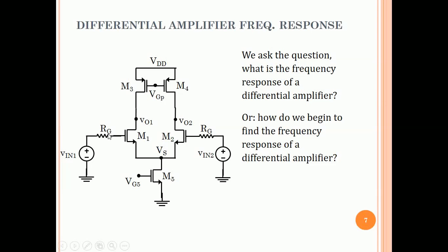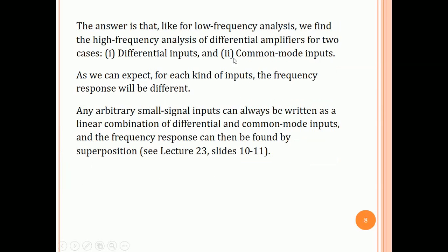The answer is actually simple, but you are given a circuit and you are asked, well, find the frequency response of this circuit. That one must first answer, how do we begin? Alright, and of course the answer is that we do this for two different sets of inputs, as we did for the low frequency case. So we find the frequency response for differential mode inputs and then for common mode inputs.